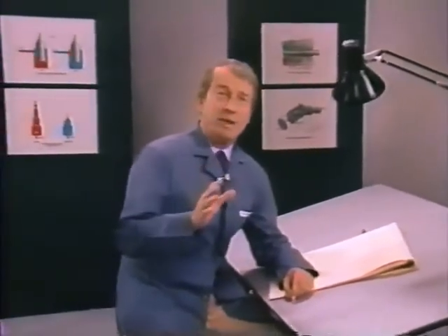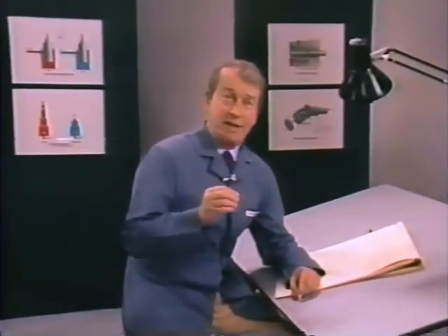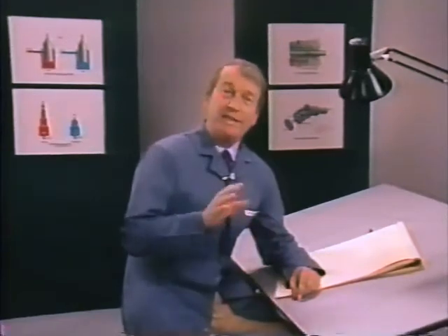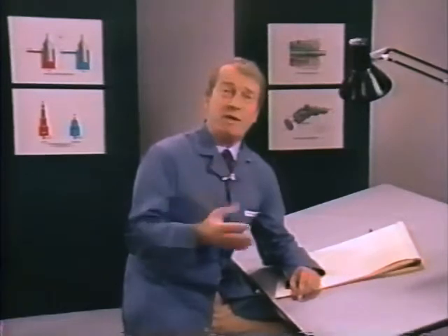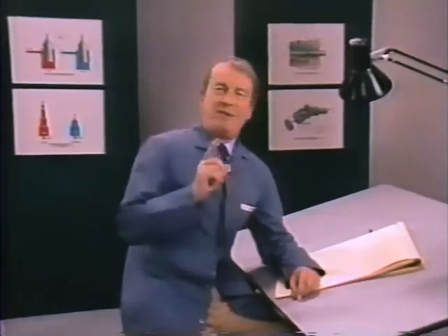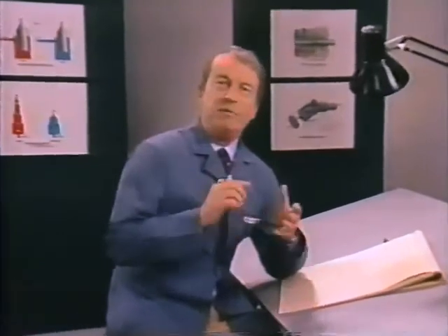Let's consider the actuator, which you might think of as the business end of a hydraulic circuit. It provides the output motion and develops the force or torque the system requires to do the work. The job to be done, in the speed, force, and torque requirements, will determine the necessary size of the hydraulic actuator to be used. If we're dealing with applications where we have straight line or linear motion, we use a hydraulic cylinder. Applications requiring rotary motion use a hydraulic motor.